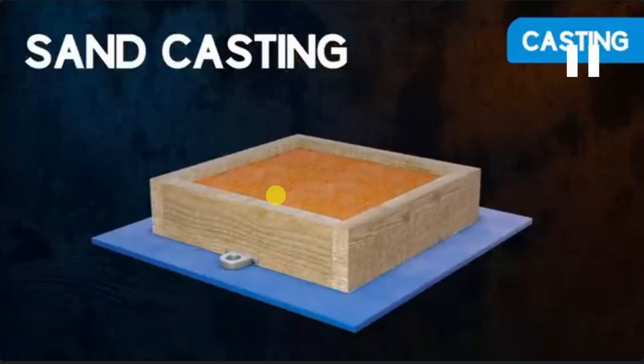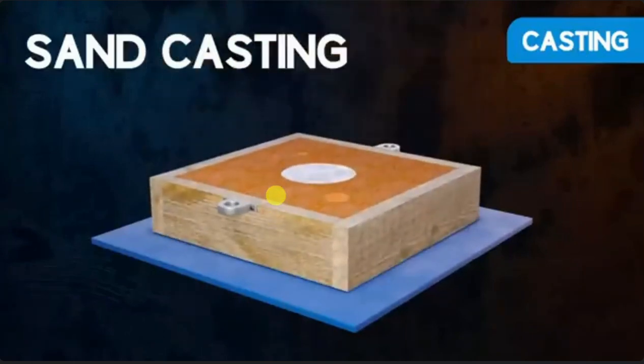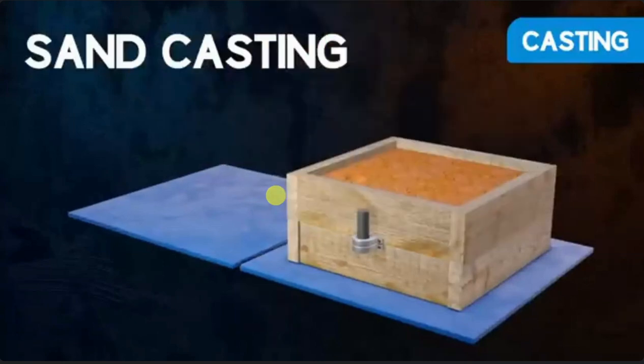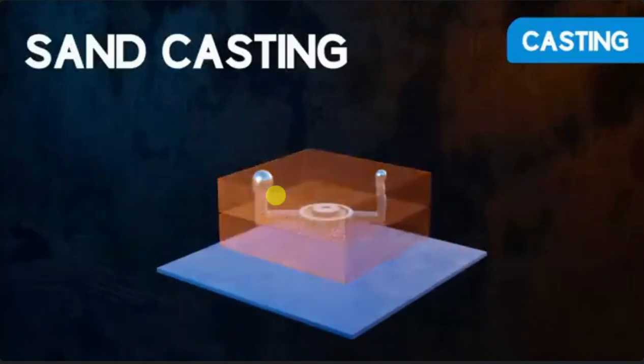The next famous type of casting is sand casting. The sand is typically contained in two mold boxes called the cope and the drag. Molten metal is poured into the mold through a channel formed in the sand. When the metal has solidified, the cast object can be removed from the sand.